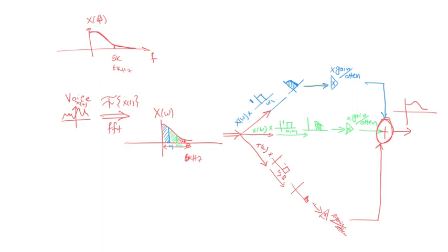Of course, given that, you don't take the magnitude and change them significantly with respect to each other. So if you decide, for example, to cancel parts of them, multiply them by zeros, and another one you multiply by 1 million, of course you're going to scramble the signal, right? But if you just do relatively close variations of the magnitude with respect to each other, and you don't touch the phase, you will still get a very nicely audible signal with those effects that the equalizer does. Reduce the sound of the drum, increase the sound of the violin and the high-pitched pianos and so on. All of this can be done by playing with those different bands, okay?